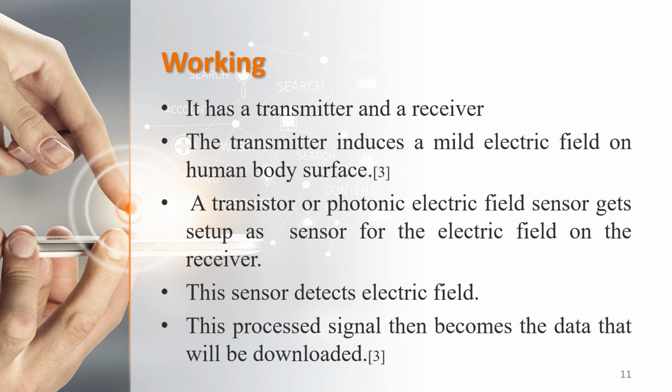Data is received using a photonic electric field sensor that combines an electro-optic crystal and a laser light to detect fluctuations in the minute electric field. The naturally occurring electric field induced on the surface of the human body dissipates into the earth. Therefore, this electric field is exceptionally faint and unstable. The photonic electric field sensor developed by NTT enables weak electric fields to be measured by detecting changes in the optical properties of an electro-optic crystal with a laser beam.